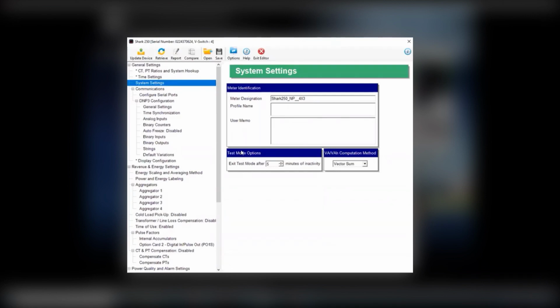The next option then you have are the test mode settings. So the test mode can be set up to 10 hours. And if you look on this screen, right now, if I wanted to put that for 600 minutes, that's roughly 10 hours I can have. And basically, the test mode allows you to take a meter out of service, perform a test to check for accuracy, and we call it calibration, to make sure that the meter is within its recommended accuracy level where it should be. If it's a 0.2 meter classification, it has to test within that classification.